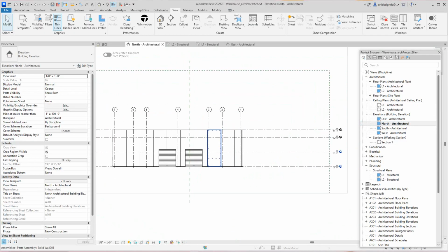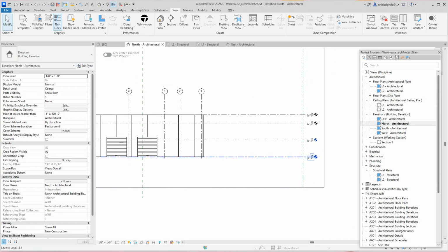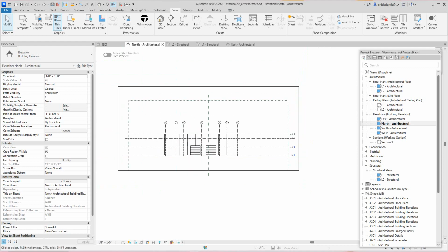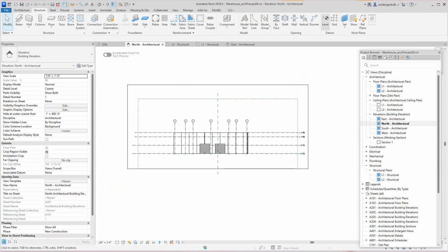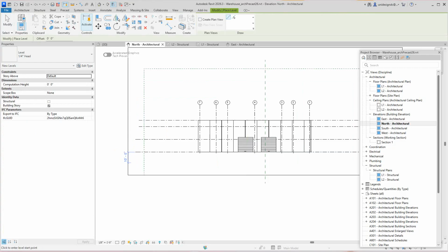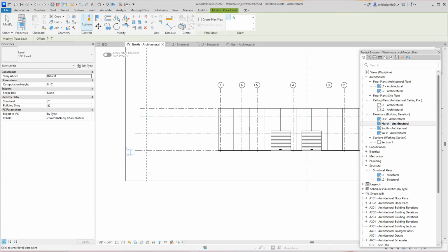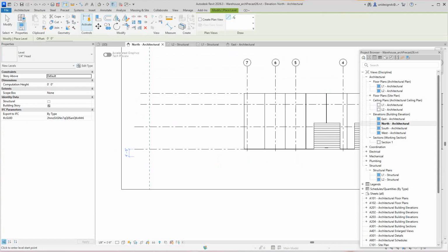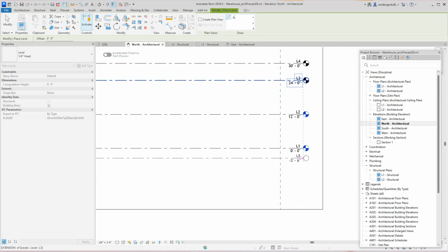Here in our north elevation, we've got our level one and our levels going on here, and then we're going to add another level. I'm going to go into structure, and we'll grab datum here. So I'm going to drop this level down to just below. It depends on the frost line. I know in Illinois it's 42 inches. So I'm going to bring this guy over and drop it down 42 inches here.